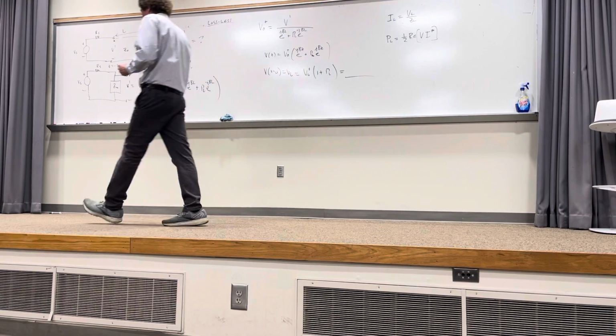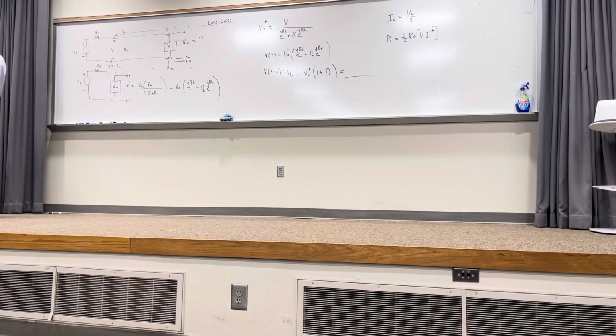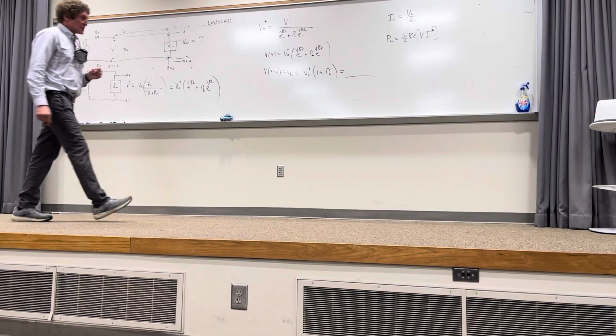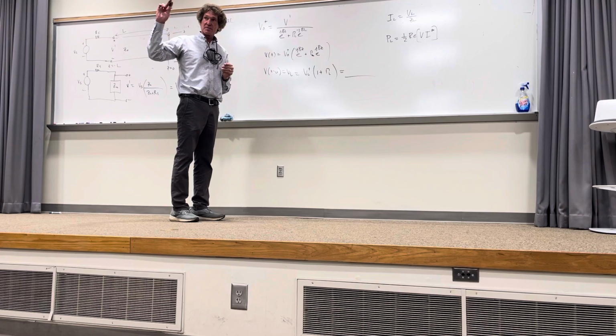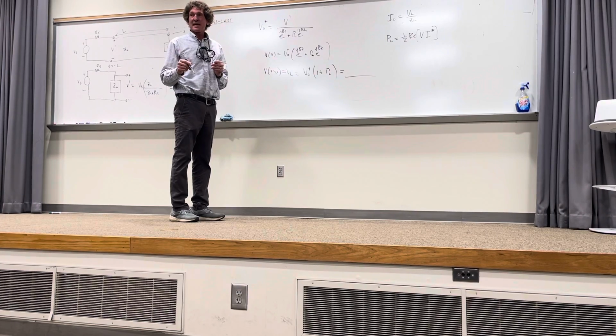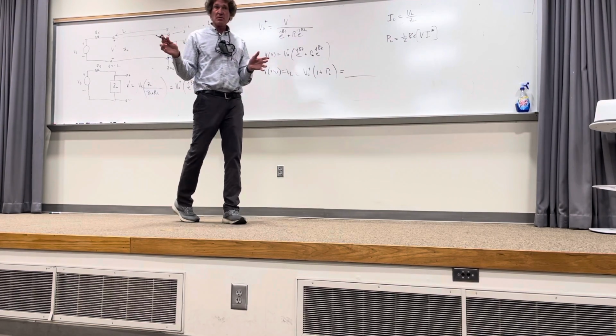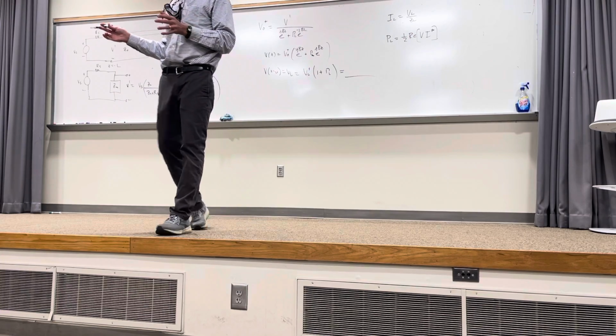So that's the whole circuit. And we can work through a problem. They're a little tedious right here because there's a lot of little steps and you have to get good with your calculators. Here's one piece of advice. Equations like this, and that impedance equation I put in there, Zn is equal to Z0 times ZL plus jZ0 tangent of B. People mess that up all the time. Get used to using your calculators to calculate and get the right answer.